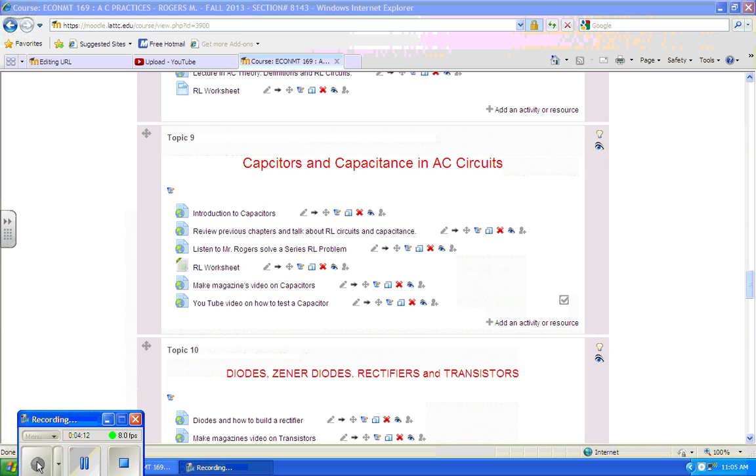Now, the second item on your list, after you check the capacitor and make sure the one you're going to use is going to work, is you're going to make sure what the actual capacitance of the capacitor is. And it says use a capacitor checker. The required meter for this class and the 4th semester class is a Fluke 117, and it can check capacitors. It has that capability, so if you don't know how to do it, look it up in the instructions of your meter. Okay? Solve problems with a capacitor connected in series and parallel. That is basically the project you're going to do.